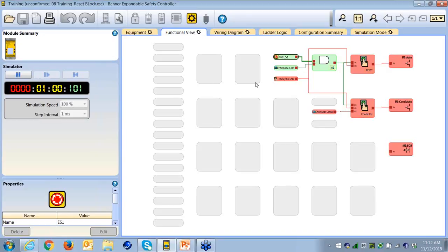So one of the options that's available in my drop-down tile is I can add a reset enable. Notice here that while this one went on with the 2 inputs high, even though I feed the same thing to the input, this one did not. And that is because I do not have the reset enable true. Let's say that you don't want to start the machine unless the hopper is full or something has returned. You have some known variable that needs to be in a given position in order to restart the machine.